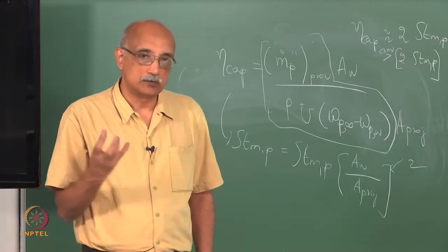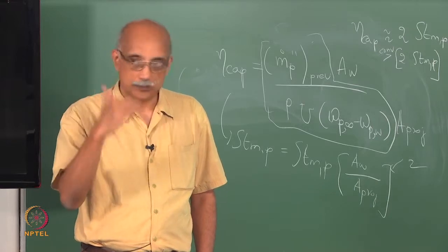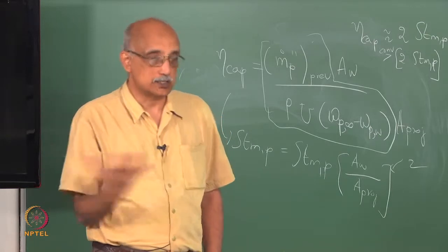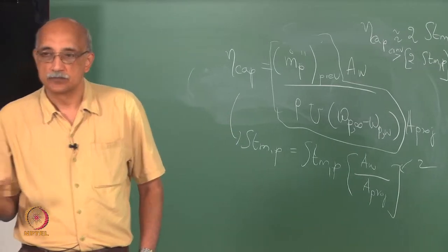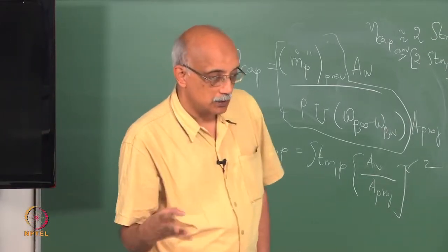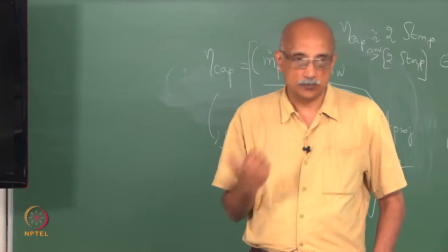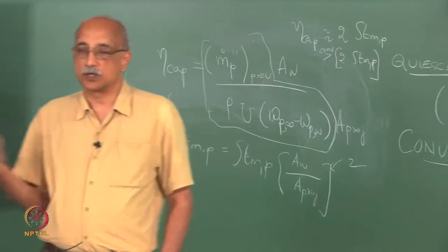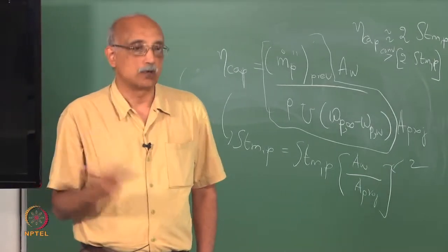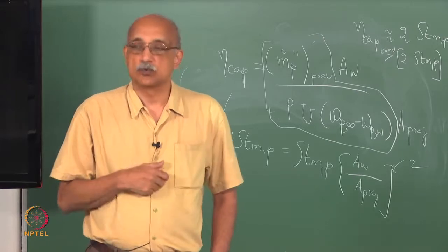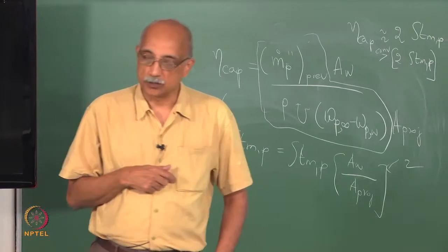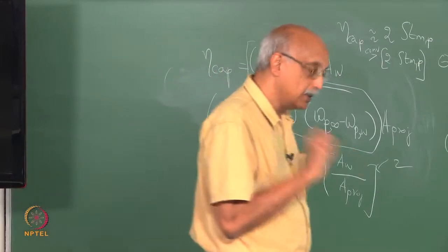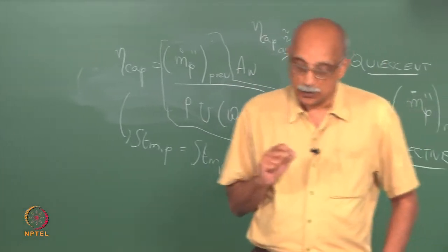Starting with the structure of the particle, which is composed of a surface, a subsurface and a core, the point we made was that the surface participates most extensively in interfacial phenomena, and the 3 interfacial effects that we focused on were surface energy, adsorption and intermolecular or interparticle forces of attraction, the so called van der Waals forces and their equivalent for particles. And after that we looked at the interaction between particles and surfaces.